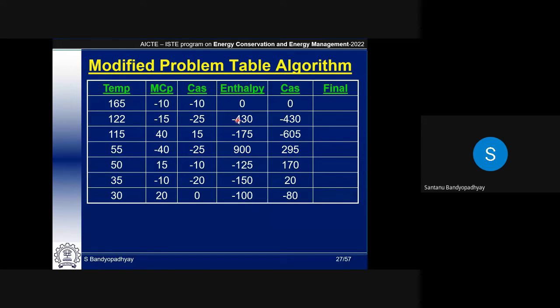Now what you could do, you see that this is a requirement, a high temperature requirement. We definitely need hot utility. And this is available if you transfer it below to satisfy this requirement, because you can always transfer heat from high temperature to low temperature. But mathematically, what we are doing through cascading is saying assume that 0 is available and I can transfer. So if I start with 0, this is sometimes called invisible cascade, I'll get a negative number, minus 605. And that's not correct, because heat demand cannot be transferred to a lower temperature. It has to come from the higher temperature. That means if I started with 605, this should have been no negative number.